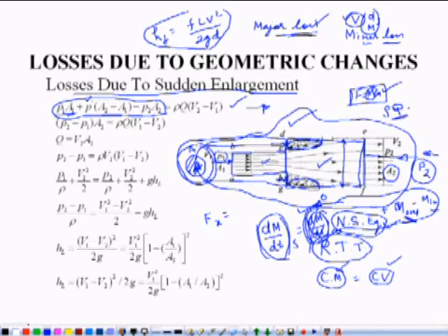Rho q multiplied by velocity is the momentum going outside the control volume per unit time. So, rho q multiplied by V2, since rho q is a constant here, flow is a steady flow. So, that is why rho q is taken outside this bracket, and momentum going outside V2 minus momentum going inside is rho q V1, rho q is taken outside, rho q times V2 minus V1, right. So, with the help of Reynolds transport theorem we can apply the momentum equation for this control volume.